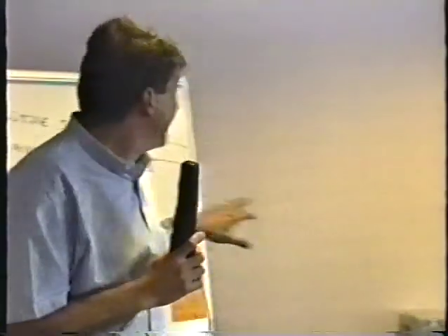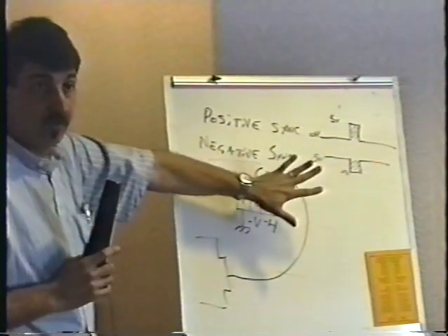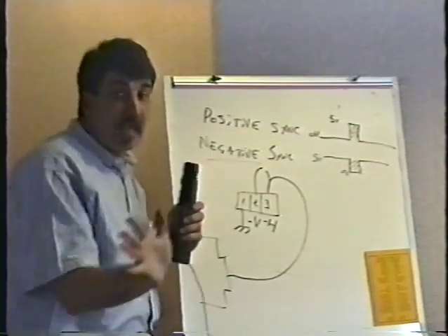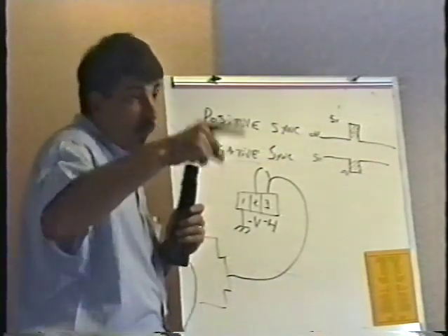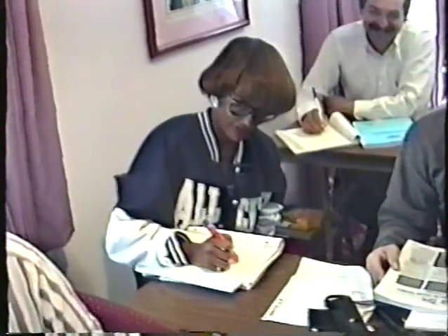When you have a problem with vertical sync, make sure that the jumper is not in there. When you do a conversion kit, here's what you do. Connect the sync to pin 3 only first. Turn the game on. If it is not rolling, leave it that way. If it's rolling, then you'll have to put the jumper in. But if it doesn't roll, do not put that jumper in.